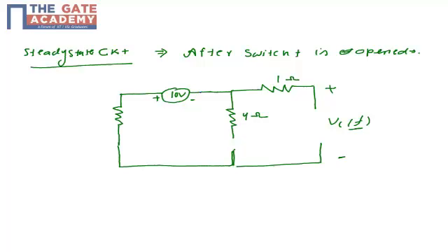The entire voltage of 10 volt will be transferred to the VC. And we can see that the negative terminal of the 10 volt is attached to the positive terminal of VC. So my VCF, or VC final, will be minus 10 volt, with the positive terminal corresponding to the negative terminal of the voltage source. So VC final will be minus 10 volt.